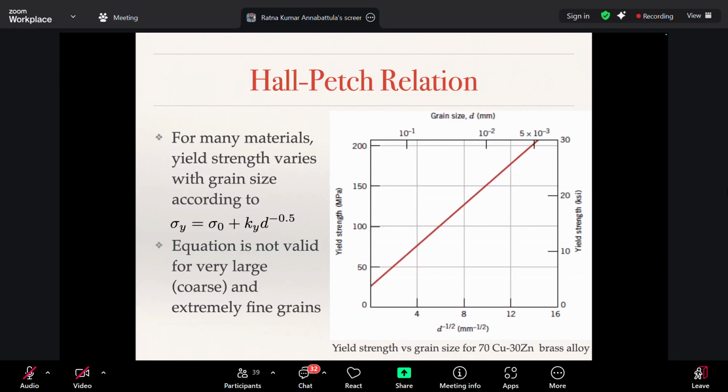So if I have an extremely ductile material, all I can do is reduce the grain size, make the material fine grained, and the strength of the material increases significantly, right? This is what we call nanocrystalline materials. So what people have done is they have made polycrystalline materials whose grain size is of the order of tens of nanometers.